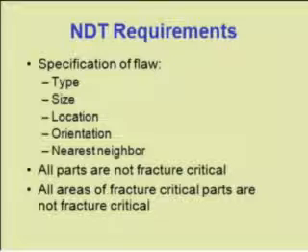There's a lot of misunderstanding on that, and within the aircraft or aircraft engine community, one of the notable engine builders said, well, we know how cracks initiate and grow, and we can put a crack size on there. What we will do is put an EDM slot in there, start the crack, and grow the crack.